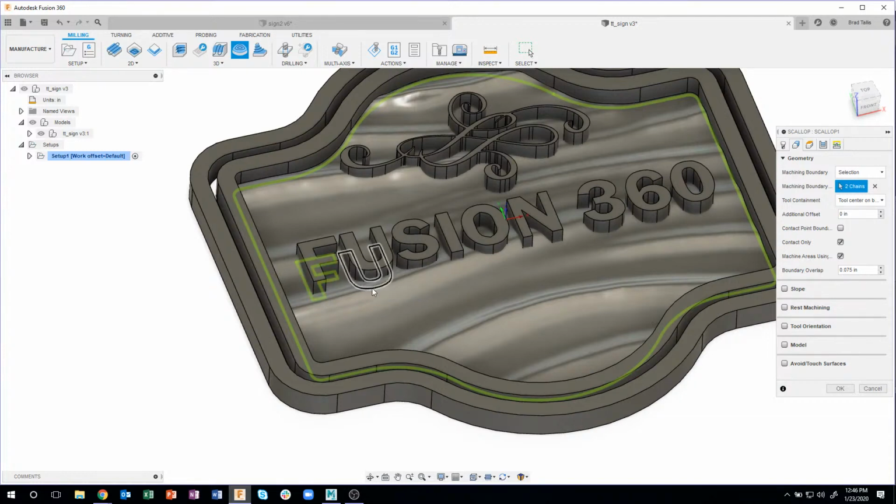So I'm just going to get near it, and you'll notice I can click on it and it highlights it down below. I want to make sure I'm not getting these individual little faces like that. I want to grab those, and I might even do that interior one, making sure I grab the tool paths that I want. Now I could also speed things up by turning off the mesh in this case, but I like to keep it visible. I'll do the same thing with this flourish.